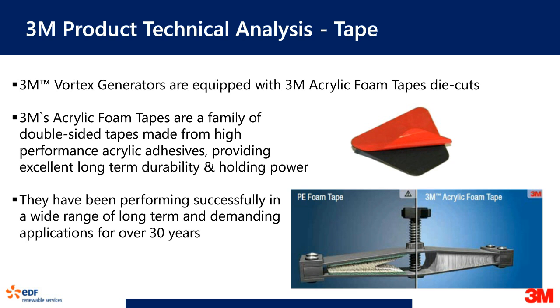So this is where we decided to go to our acrylic foam tapes. The acrylic foam tapes are high shear adhesive tapes with a very strong foam closed cell core, which gives the flexibility that you need for these different conditions and also the coefficient of thermal expansion, coupled with the strength that you need for it to withstand very high forces and changing weather and so forth.